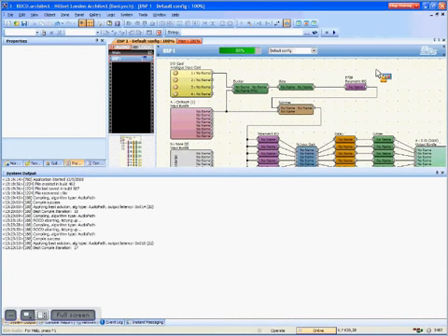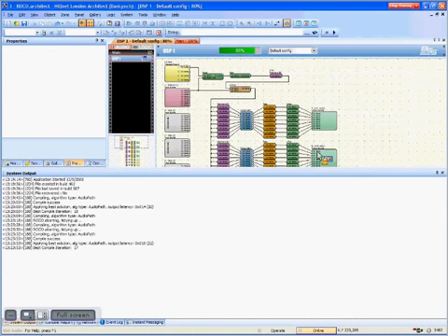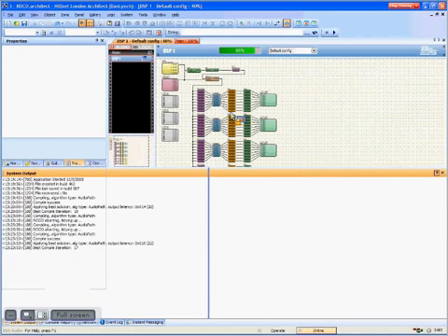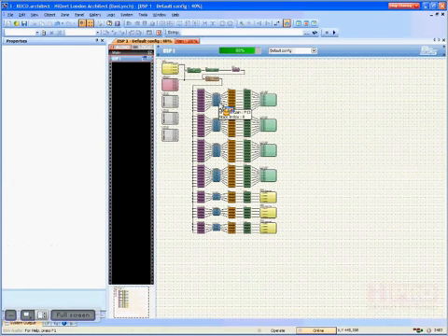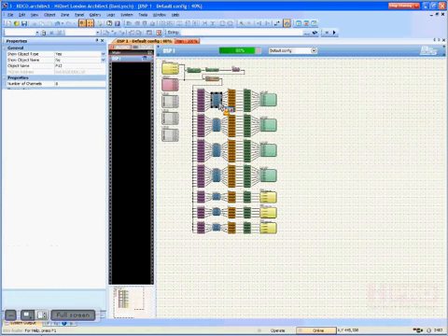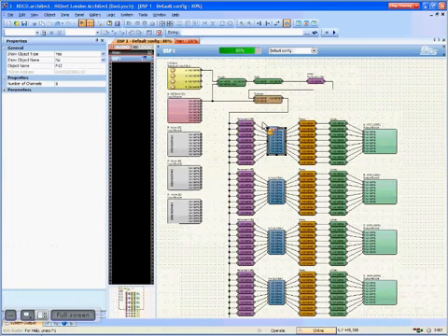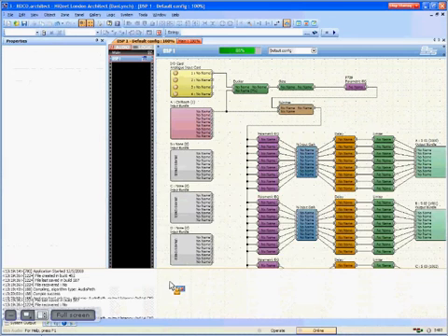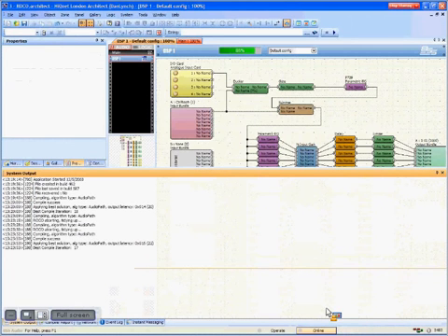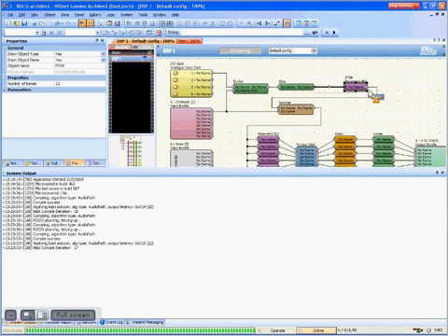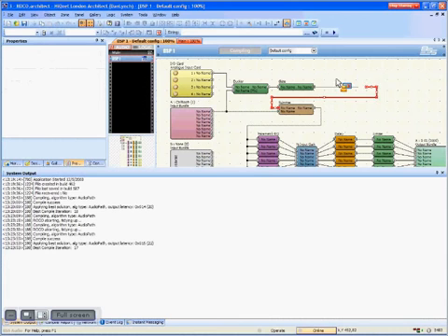And this, just so you know, is a fairly chunky design file. This is processing for 44 output zones in a dome. 44 output zones that all have EQ, gain, delay, and limiter, each of 44 zones. So it's not a cheesy little easy design file to deal with. Take that EQ back out, it starts compiling again. Fire that up, and abort, start over again. And somewhere between 6 and 18 seconds later, I have my result.